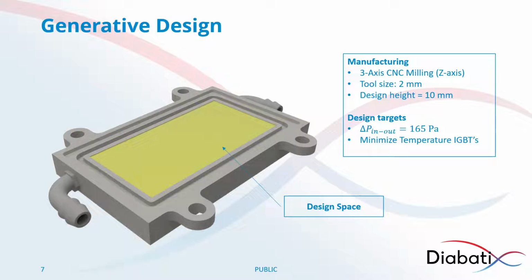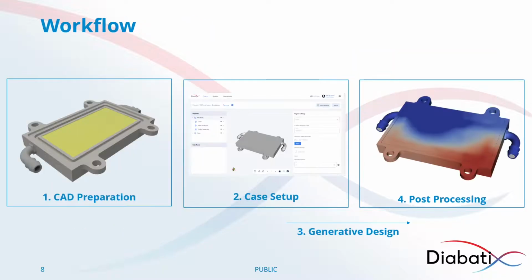So this is a small summary of how the case looks. Let's have a look now at how we will approach this. First of all, and that's what I will show in this webinar as well, you need to prepare your CAD file. You can do that in your own CAD environment. I will be using Autodesk Inventor for that, since that's our CAD tool, but you can, for instance, also use your CAD tool. As long as you can export a step file from there, it's good.